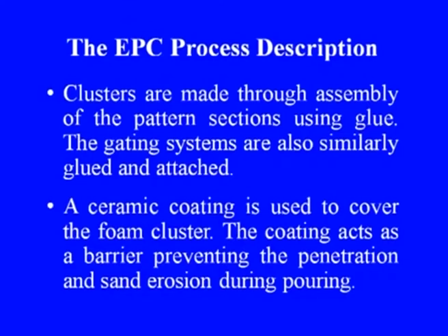Clusters are made through assembly of the pattern sections using glue. The gating systems are also similarly glued and attached. A ceramic coating is used to cover the foam cluster. The coating acts as a barrier, preventing the penetration and sand erosion during pouring.